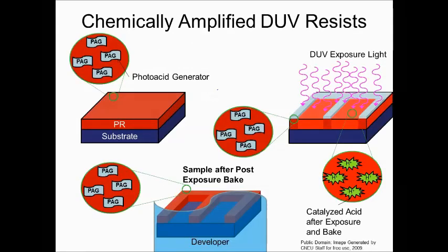details of that. But basically what we do is we apply it. So we apply it, and then inside the chemically amplified DUV resist, we have this thing called a photoacid generator. So the photoacid generator is embedded in the resist, right? And the photoacid generator is step one to get our work done. So it's sitting in there. The light comes on, and it actually turns the switch on chemically in the photoacid generator. And the photoacid generator is weakened by the light.